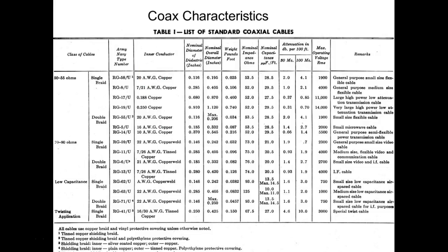So that means I could have a 75 ohm cable that's got 75 ohm impedance, and then it might have so many ohms per 1,000 feet. Well, when I start pushing signals through ohms, it's going to drop the voltage too, right? So if I have to send it over a bigger distance, I could still use a 75 ohm impedance cable, but the cable would be bigger.